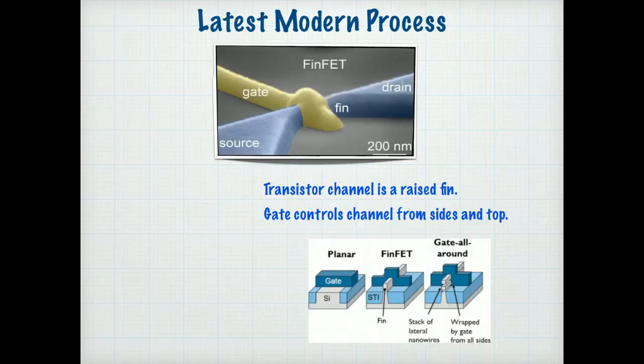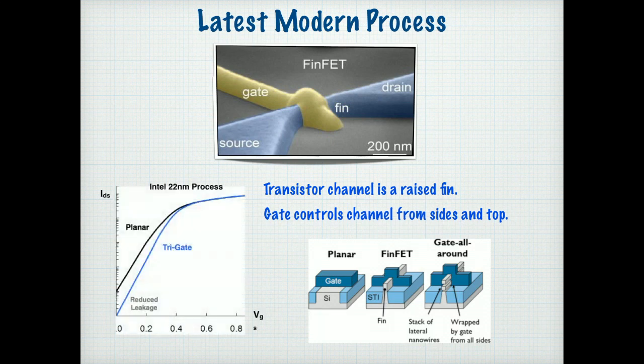Okay, so back to one thing. Now back to FinFETs. The one thing that FinFETs did is they changed, because of the shape of the transistor, the electrostatics, and it changes this property of the curve, the so-called subthreshold slope, which is the slope of this curve measured on a log plot.